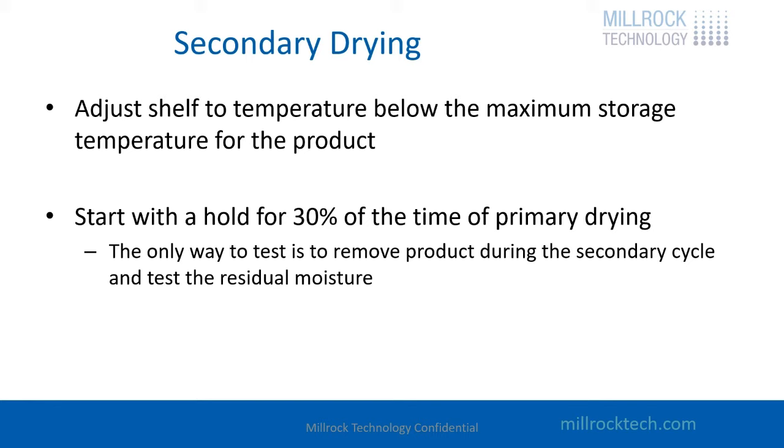In a vial, obviously we're sealing the vial with a stopper under slight vacuum. By the way, it's under slight vacuum, not heavy vacuum, because if there's too much vacuum in there, it will also tend to draw any moisture in from the residual air around it.